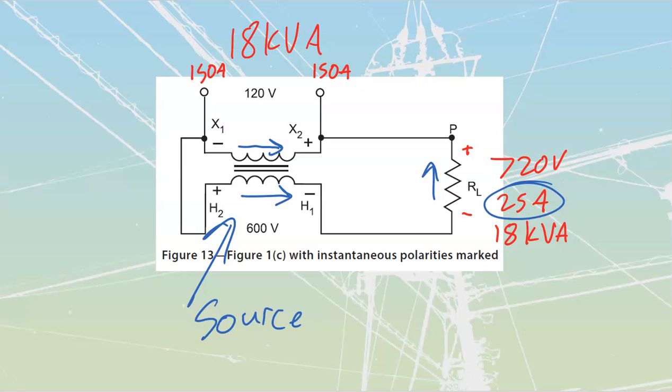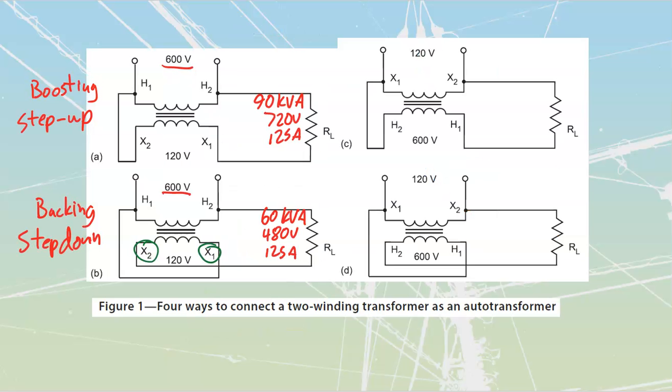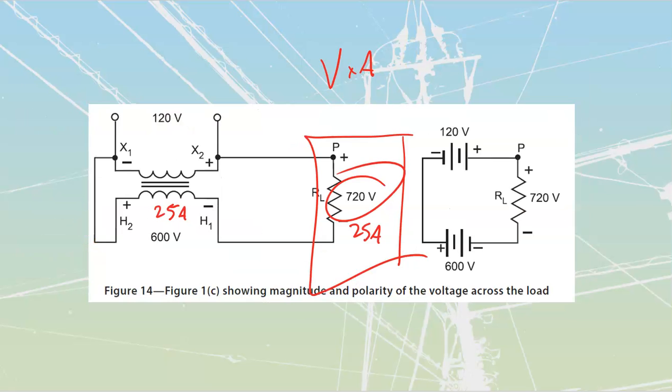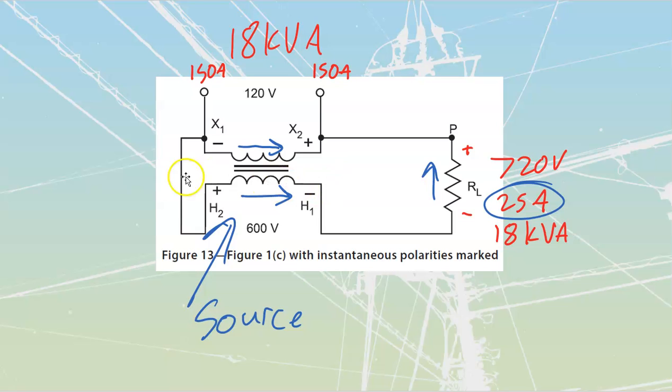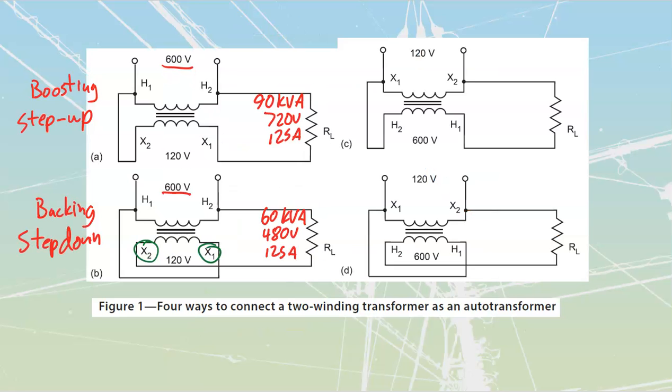All right, let's carry those values up top to this one. So at this point now, we have got a connection. I don't know if actually we defined that. We'll just go back down to this one here. We didn't define if this was bucking or boosting, but if I take a look at what I'm putting in, 120, and what I'm getting out, I see that it's the sum of those two. Therefore, I know that they're aiding each other. Therefore, I know that this thing has to be a boosting type of configuration. Let's write that over here.